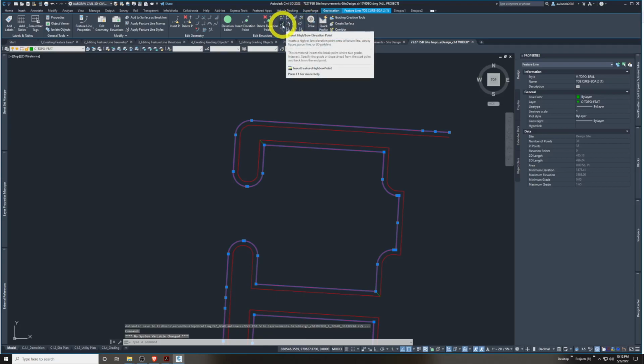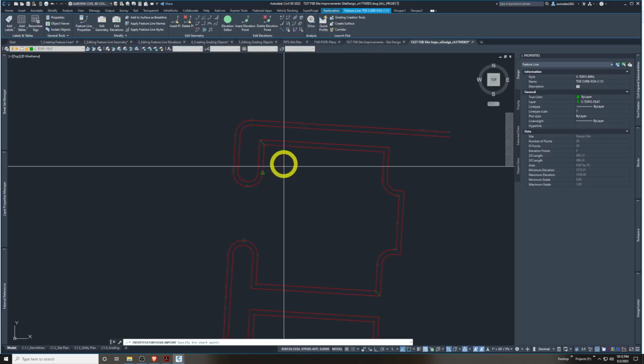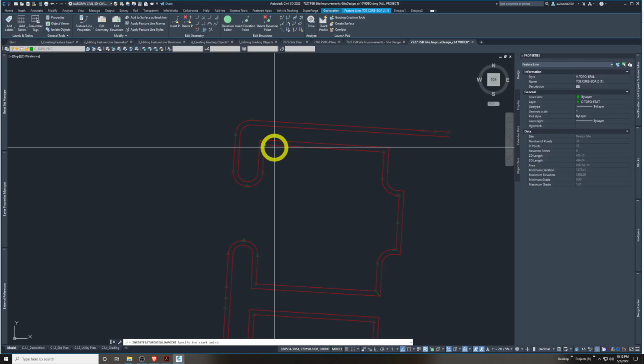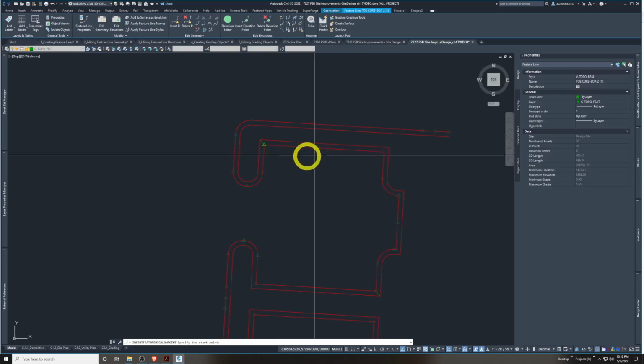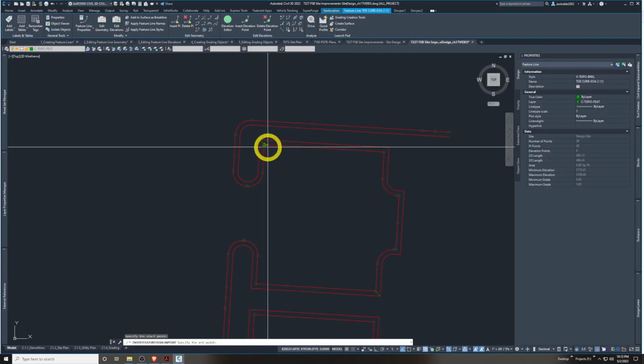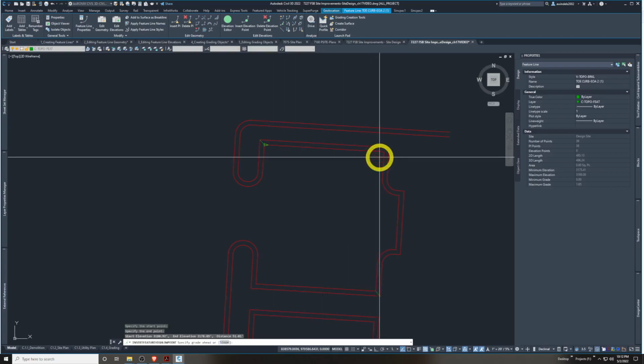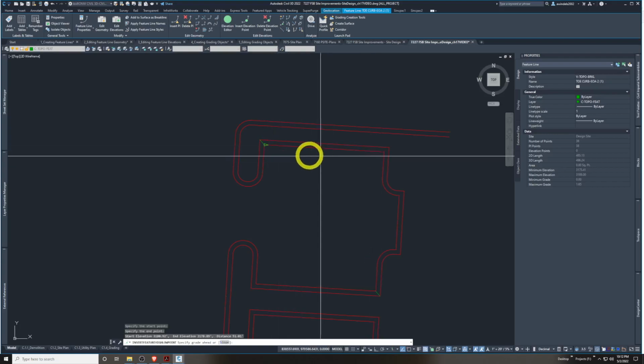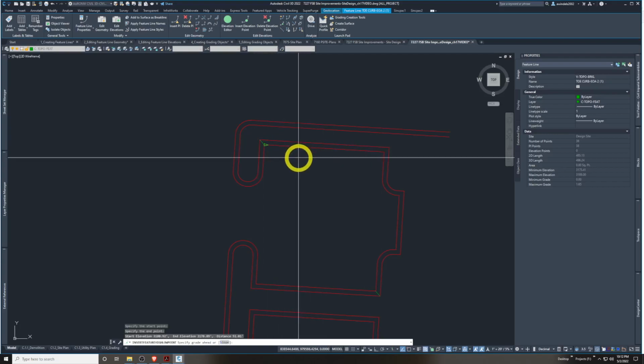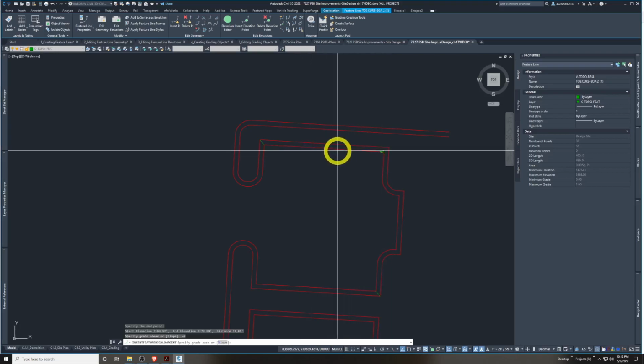I'm going to insert a high and low elevation point here. So this one, you pick 2 points basically. So let's just pick here and here. I'm going to say this is my start point, this is my end point. So my grade ahead, this direction, let's just say is 6% or negative 6%. And my grade going back, we'll say is negative 4%.